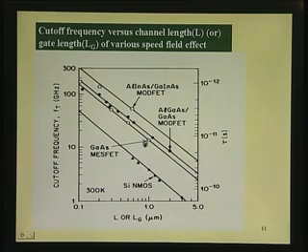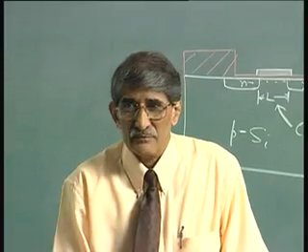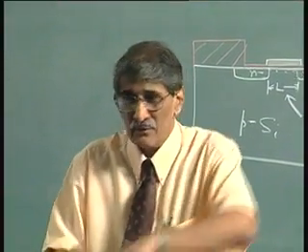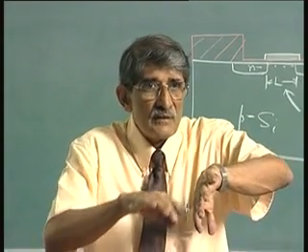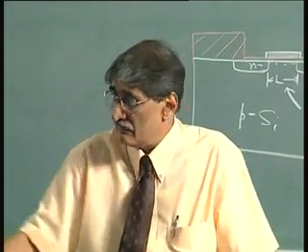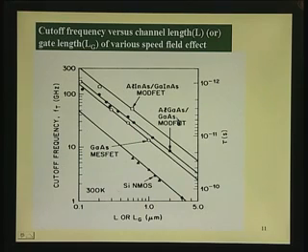In fact, this is where the trick is done. The trick that I was mentioning: separate the electrons from the dopants. Electrons are confined to this gallium arsenide layer and the dopants are confined to the aluminum gallium arsenide layer, a ternary compound. What it is we will see later, but two different materials. So, electrons are confined to that high mobility region. So, the ionized impurity scattering is removed from the picture or reduced.